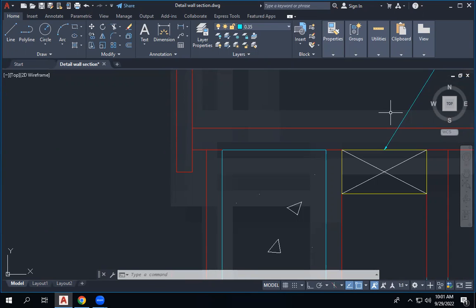Colors can be changed because I just give the line thicknesses. There is another way of doing the line thicknesses. AutoCAD itself has a grayscale plot style. It has some colors with different grayscale. For blue, it gives a darker shade of black. The others have more grayish colors, like yellow gives a lighter gray, something like that. But I used to use this line thickness method. That's easy. How big is that? It's like this, the 1 inch, the same thing.